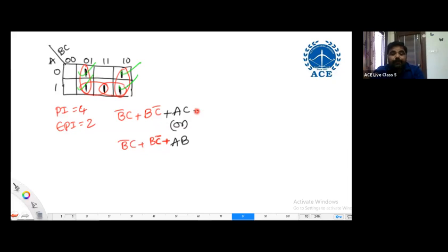Once again, I'm repeating. Please give your 100% presence to my words; you will understand. I'll make a note. If there are minterms which are not covered by essential prime implicants, to cover these minterms we are choosing non-essentials. While choosing non-essentials, again we are observing multiple ways, also with the same complexity. Then we are getting multiple minimal expressions. Let me make a note.